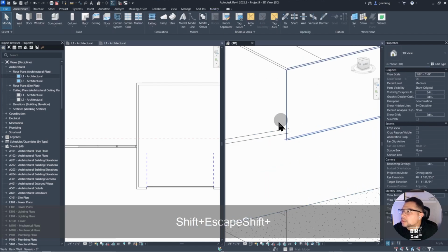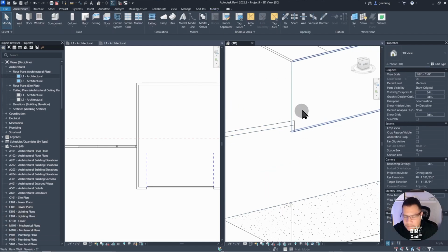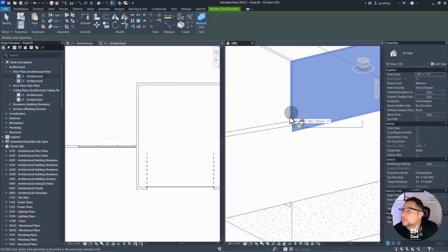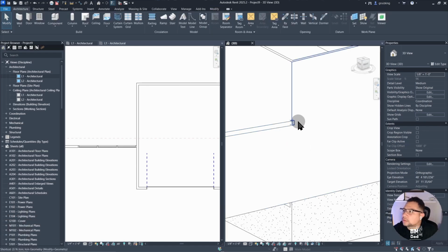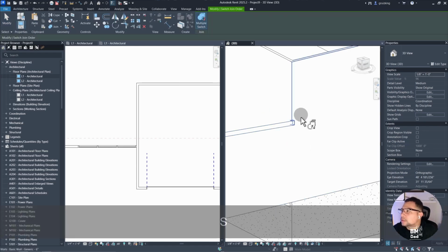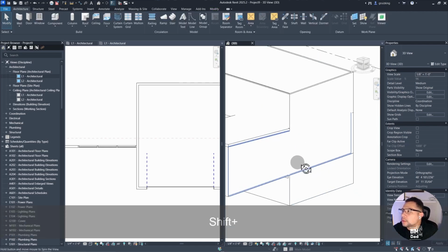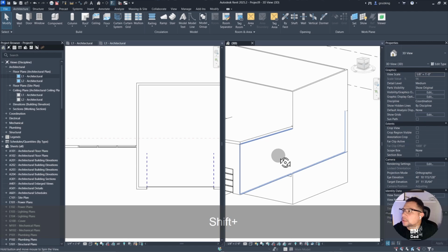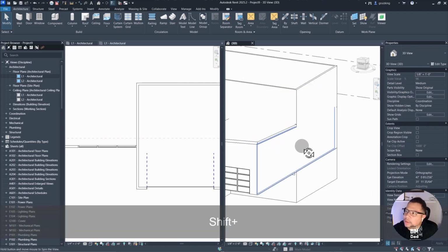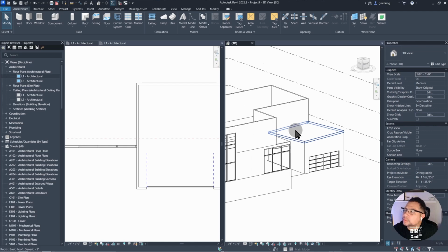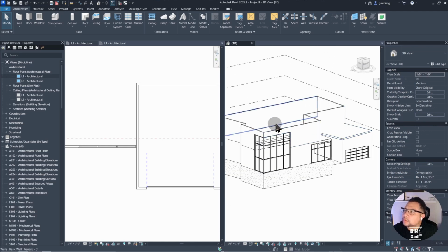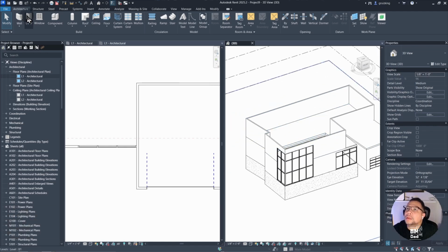So you can see there's a little bit of overlap here, and that's just some cleanup that we can do by just joining walls. Same thing with the roof, and if that looks wrong, I'm going to switch the join order there to clean it up. A couple of tricks there on just managing the walls and joins, but yeah, that's a simple roof that we can show there. Now let's go up to the top and let's start with a flat roof again.